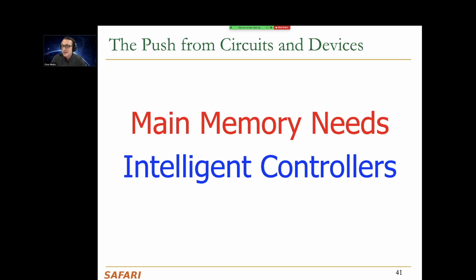about. But I will quickly mention that to be able to solve this problem, you need some intelligence inside the memory. I believe the memory controller is a good place to put that intelligence, so that the memory controller understands what's going on. And there are multiple approaches to this problem, clearly. You could potentially figure out whether an attack is going on, or you could try to intelligently refresh different parts of memory to ensure that an attack doesn't happen. But these are both different types of intelligence that you add to the memory controller to fix the issue.